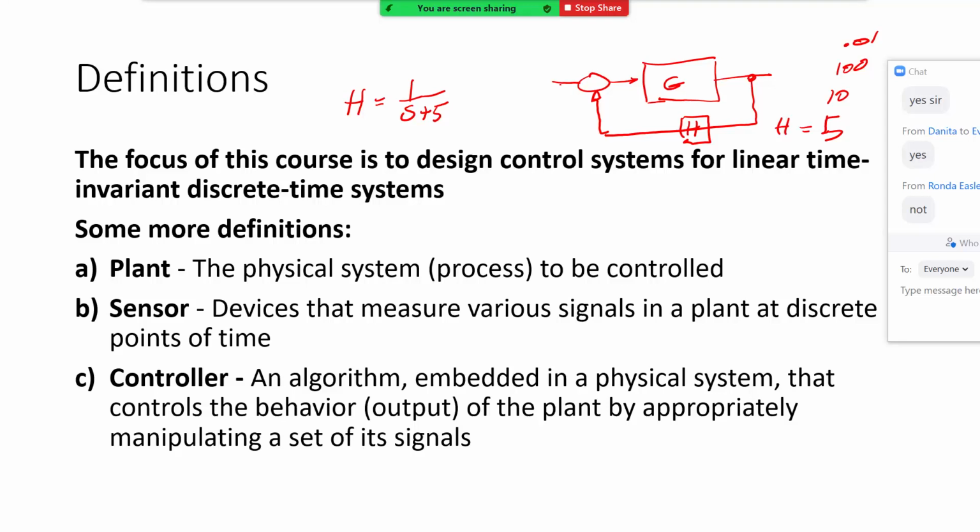If I'm trying to control the motor and I want it to move, you know, pi over 4 in 1 second, then I'm going to get a sensor that will give me a measurement in millisecond or microsecond. And therefore, the speed of the sensor is much, much faster than that of the system. And therefore, I can just approximate it by a constant. Is that clear, everybody?